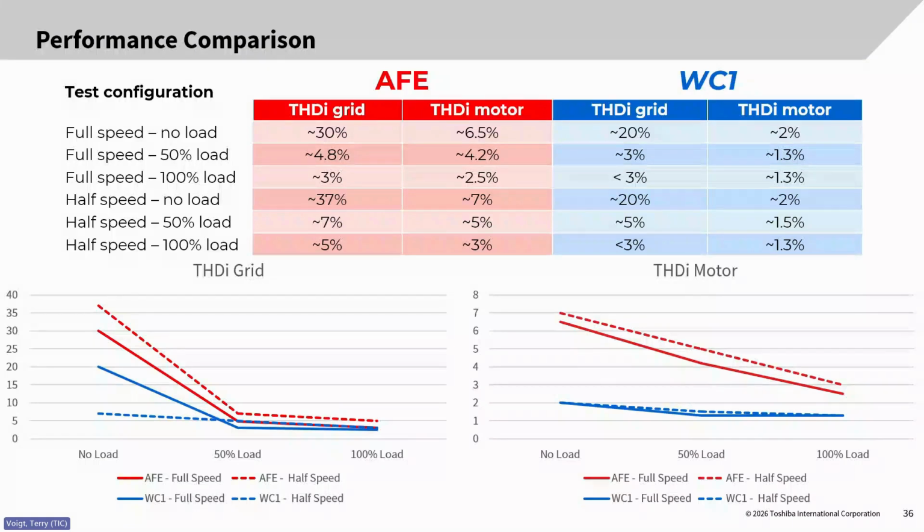That's the result of the sine wave filter that's built into it. We have very, very little THDI, so current harmonics on the output, because we're sending out an actual sine wave form instead of a PWM waveform.